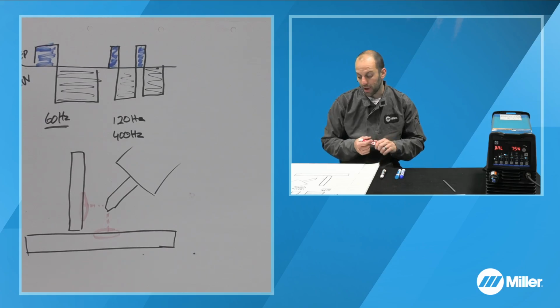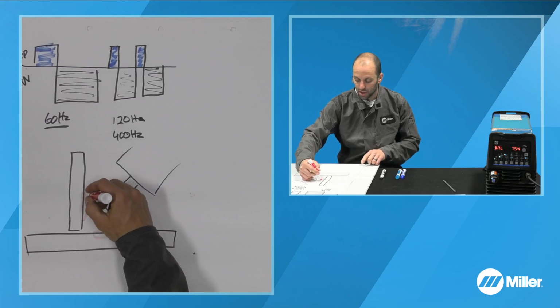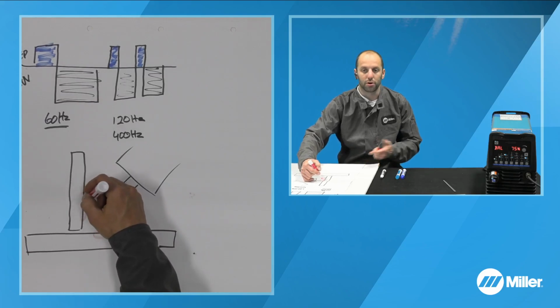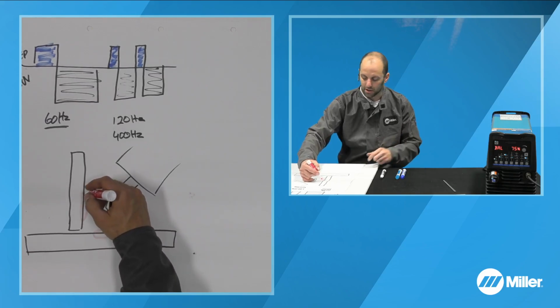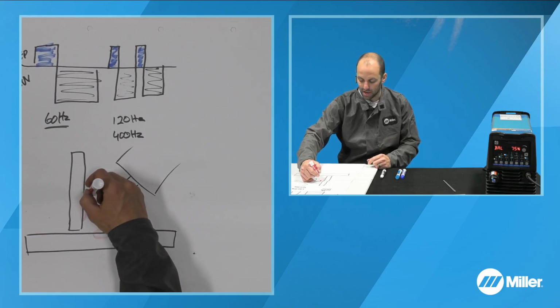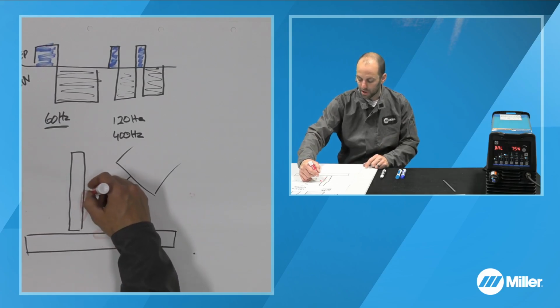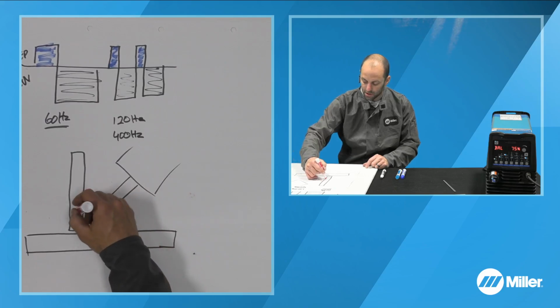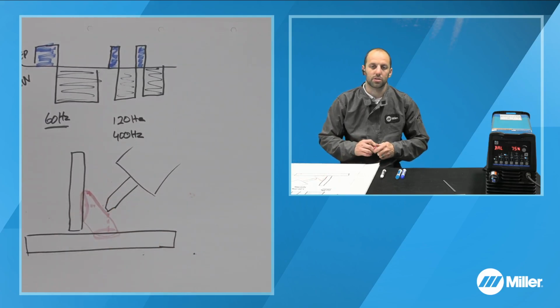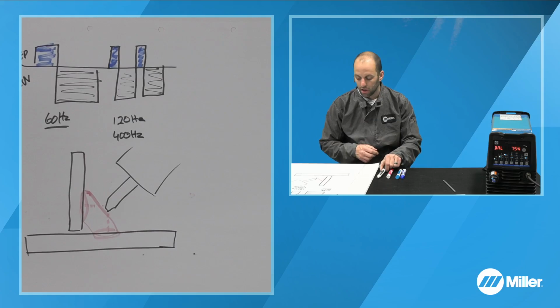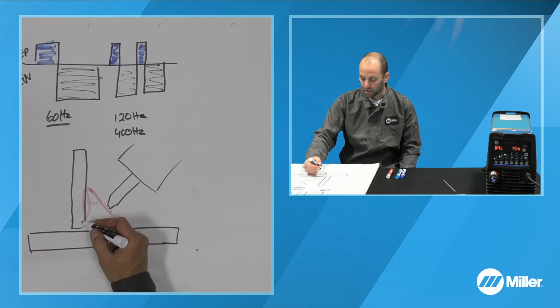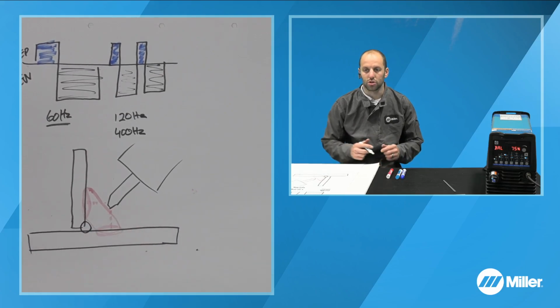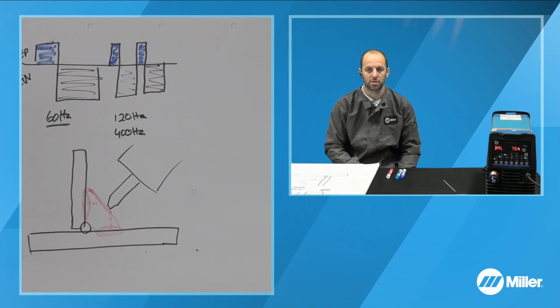So what ends up happening in this case is you maybe throw your filler metal in there, and we'll try to demonstrate this later if we have time. You end up throwing some filler metal in here, and you get a weld bead that looks something like this. Now, what do you see wrong here? We didn't consume the root of this weld or have fusion all the way to the interfaces of those two parts.